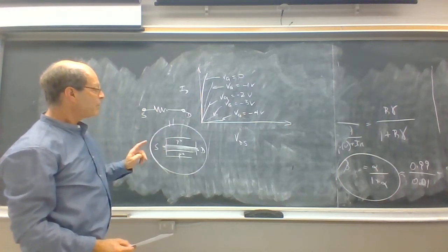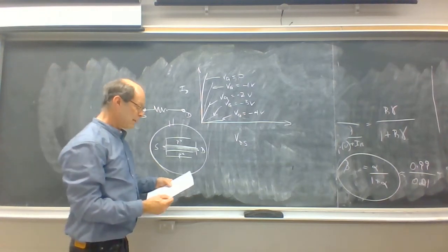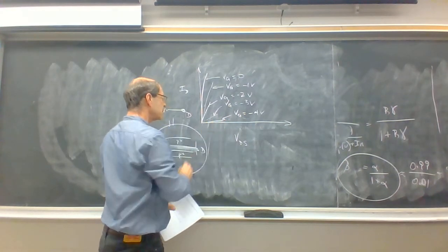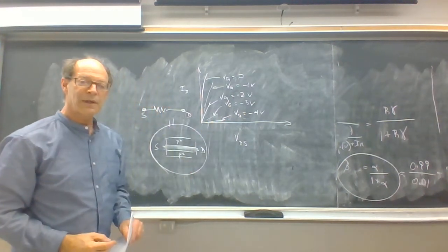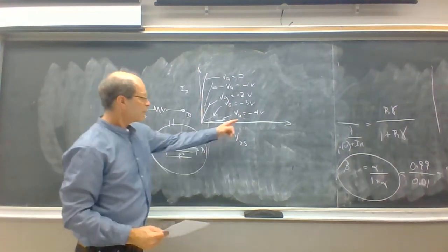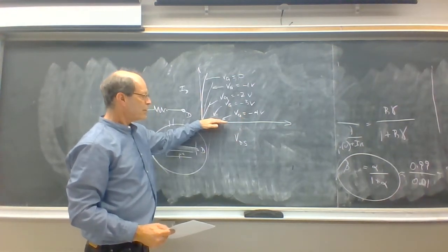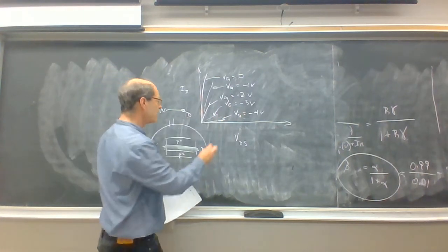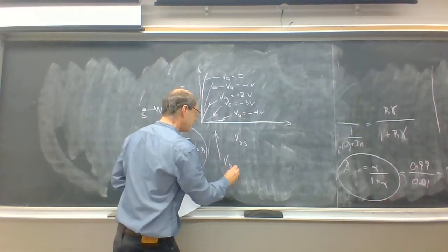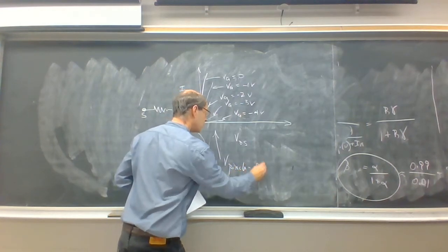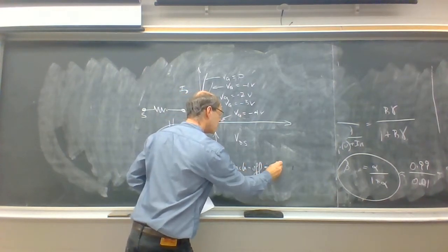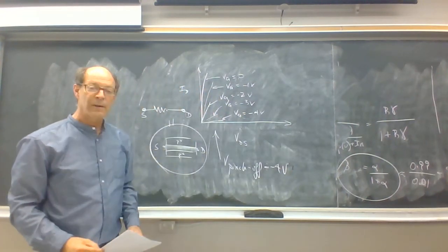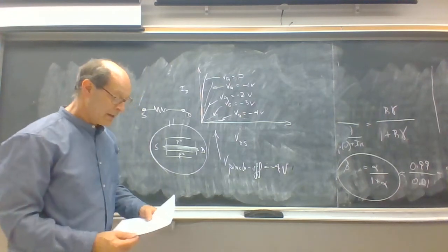What's interesting is that you can reduce the conduction through the channel down to virtually nothing by increasing the gate voltage to the point where you have pinch-off. So in this particular transistor, minus 4 volts represents the pinch-off voltage on the gate.